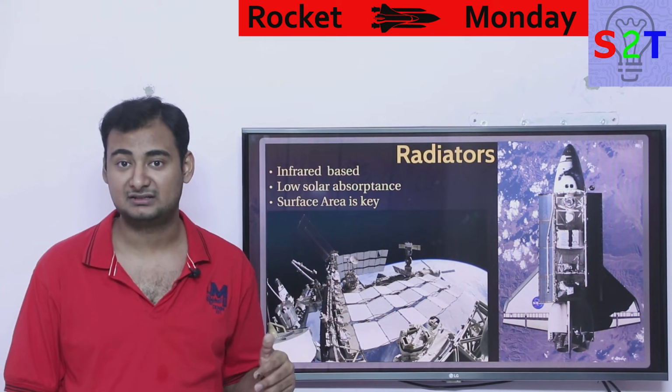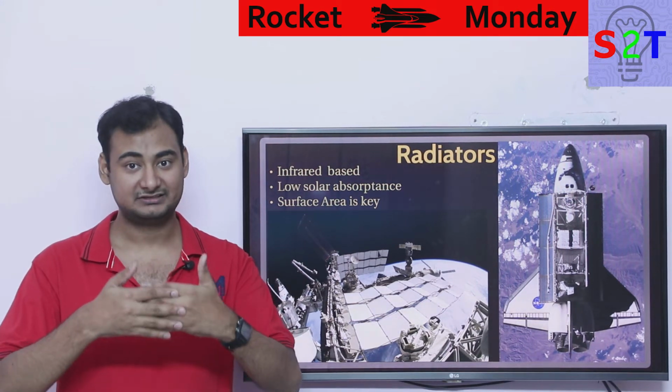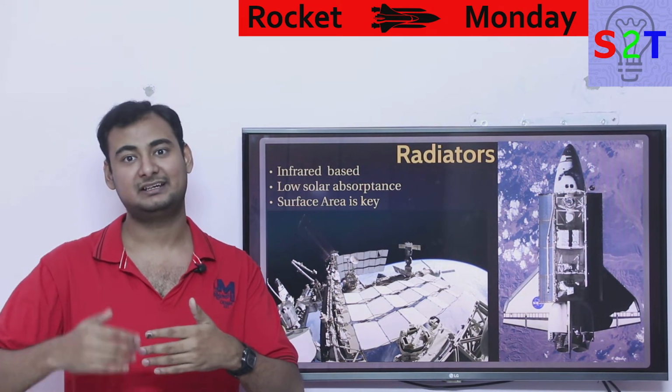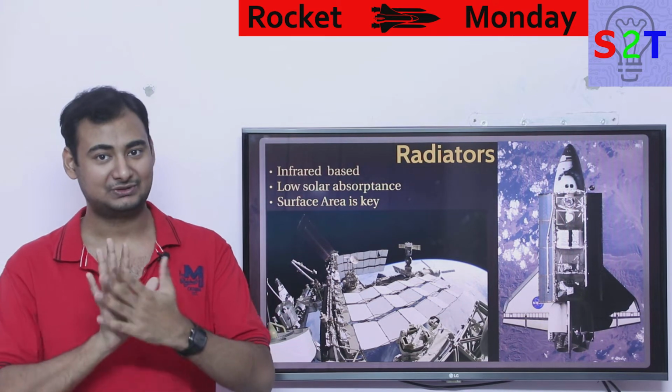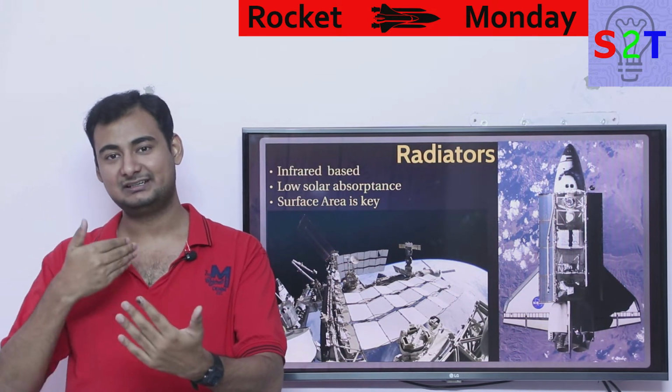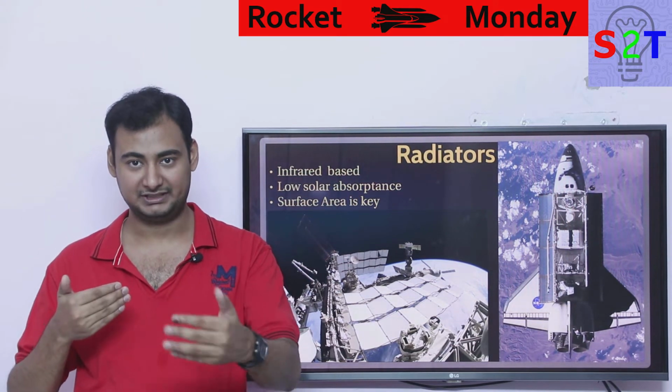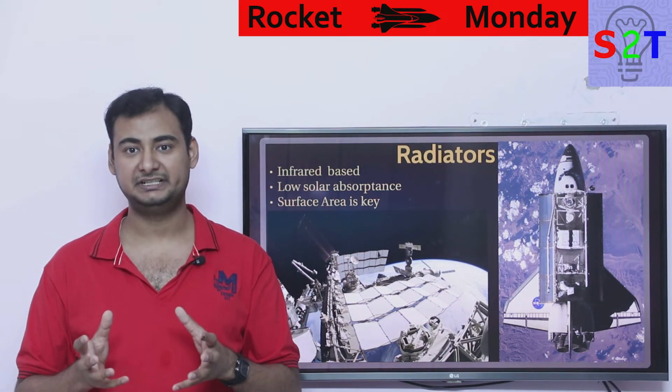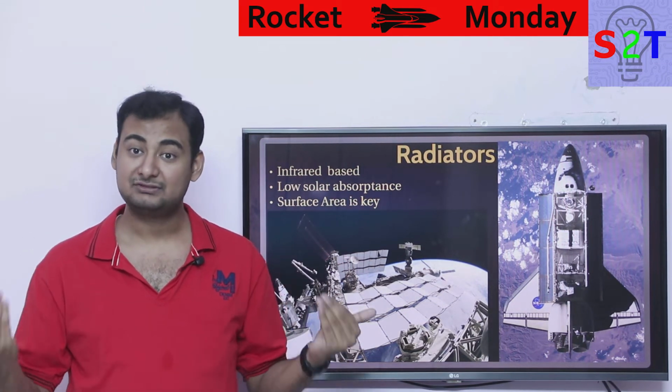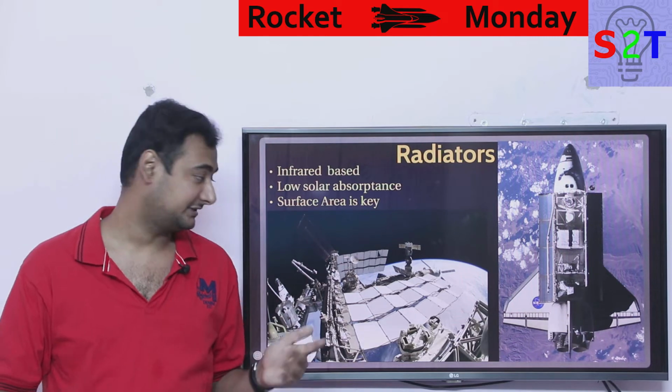And like in case of Parker Solar Probe, the radiator that it has, because at that distance X-ray and gamma rays are big enough that even though you can have a giant thermal shield, it will still have enough of the radiation that makes it through the heat shield that your components will heat up upwards of 200 degrees Celsius. Now you have to dump that kind of heat, you have to have radiators, something like this.